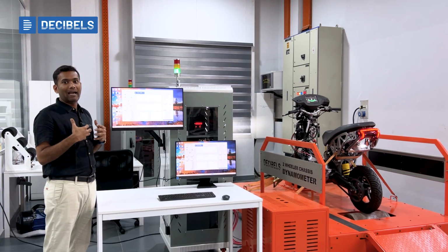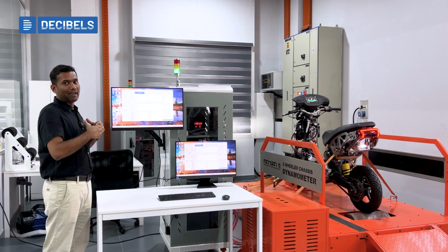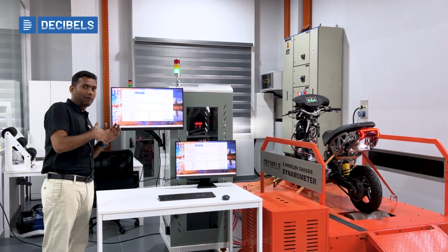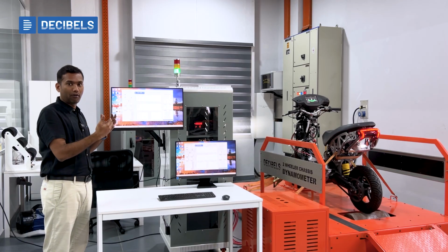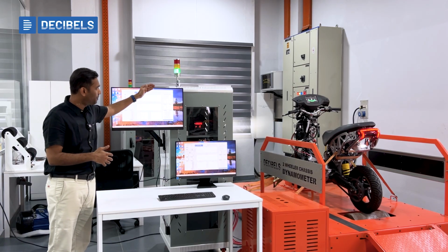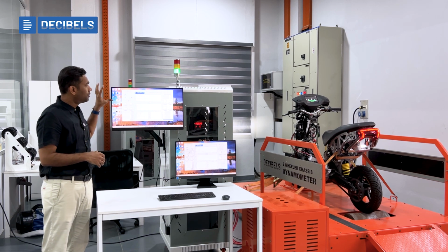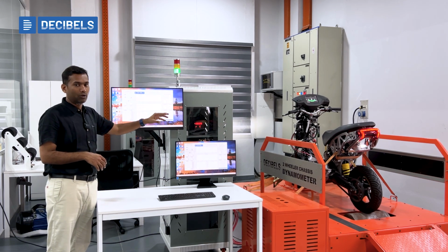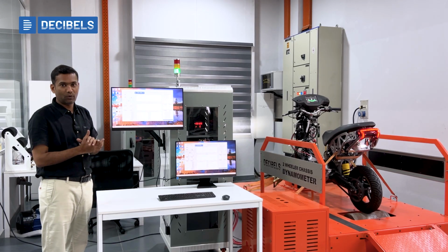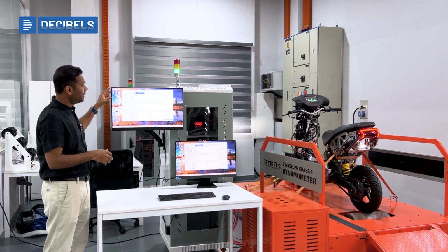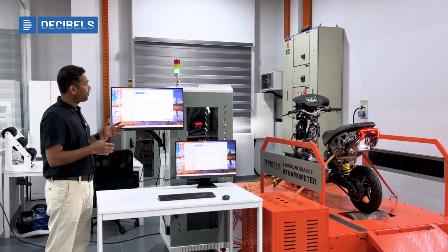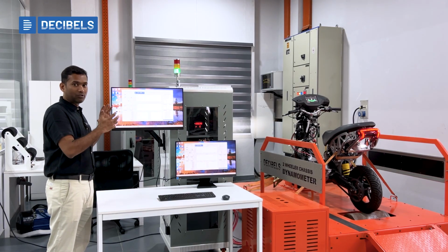We can perform acceleration test cases under various different load conditions. For example, if you want to perform at a specific grade, you can do that. You would like to apply, let's say, 2 people sitting on the vehicle, you can change the parameters inside the software, and the software will automatically apply the load from the 4-quadrant load to the roller and then to the wheels as well. We can perform test cases such as the continuous test for 30 minutes. We can also perform tests such as road load simulations.